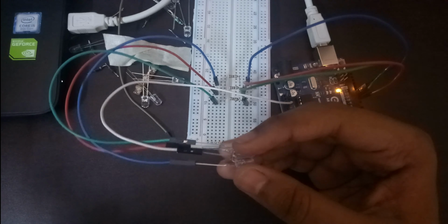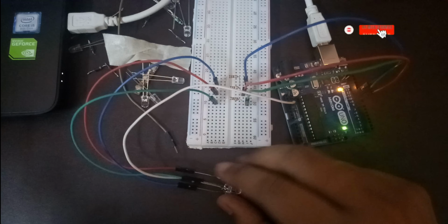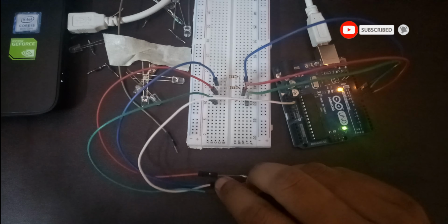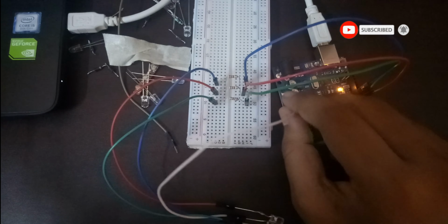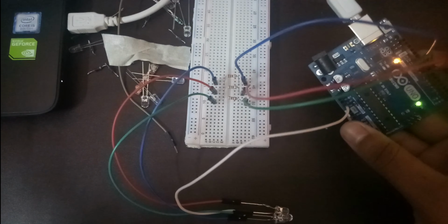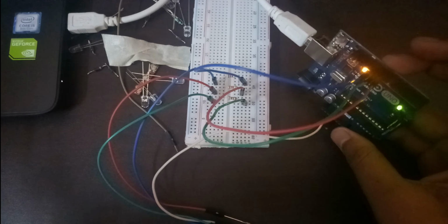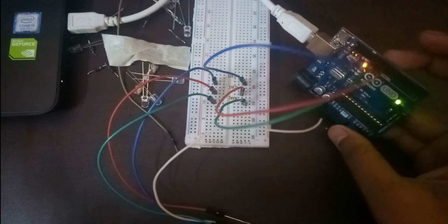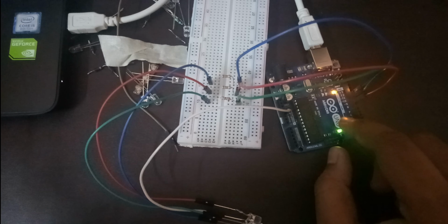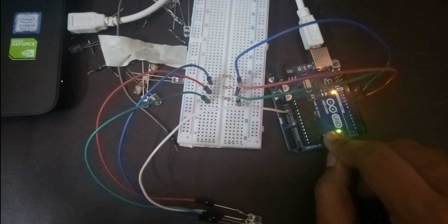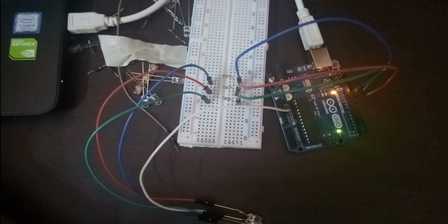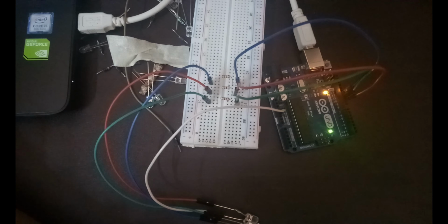As in the previous video, you know how to connect a resistor. We connect a resistor for each pin, and we use this to connect the supply, the 5-volt supply. We could use 3.3 volts, but I just use 5 volts. And it will be pins 9, 10, 11 because these 3 pins are PWM pins. That's why we're using them. So let's see our program.